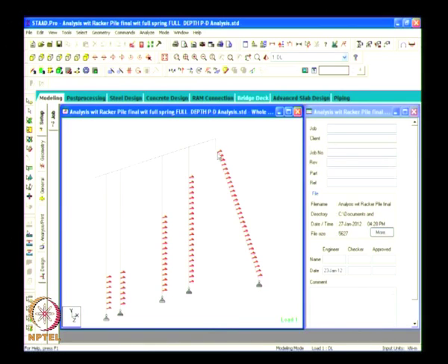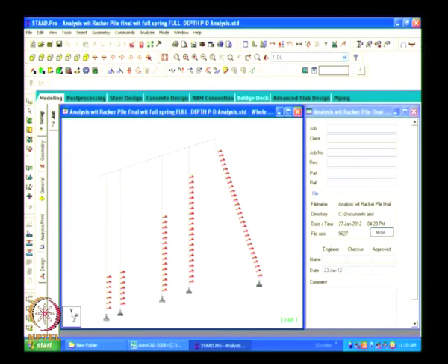The springs are starting at different levels depending on the active edge we are assuming, the 45-degree line we are assuming. And then at the bottom we are assuming a hinge condition, this is to model the rock where it is getting the embedment. So rock can be assumed as a hinge support, that is why we are giving this, and then we will show the various forces considered in the analysis.